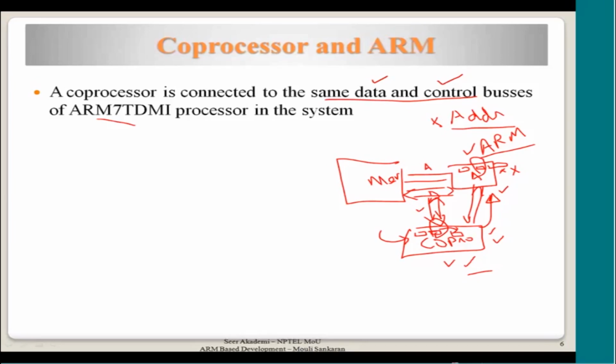Then you may wonder what ARM does. It will go on with the next instruction. It will ignore this one, knowing that this instruction is a special instruction. ARM doesn't even know whether it is going to take 2 cycles or 10 cycles or 50 cycles. It doesn't know, because it is totally implemented by the coprocessor. So it could be some internal e power x operation which may take a longer time. ARM will carry on with its own job, and the coprocessor will perform the e power x operation and then store the result in its own internal register. So that is what happens.